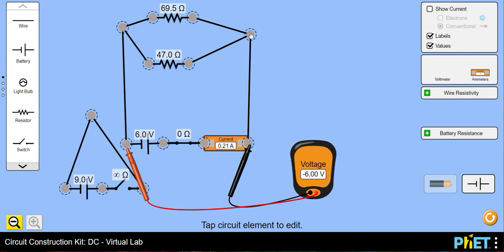A junction is a place where current can go both ways. Let's turn it on, and you can see they're going faster in one loop than the other because the resistance is lower, but there is current moving into both. That's a junction. Any circuit with a junction is a parallel circuit or has a combination of parallel and series. And that's the last one you have to do. You have to do a combination circuit. In each case, you'll calculate your effective resistance using the nominal values, and you'll compare it to the measured resistance, just as it says in the online lab.